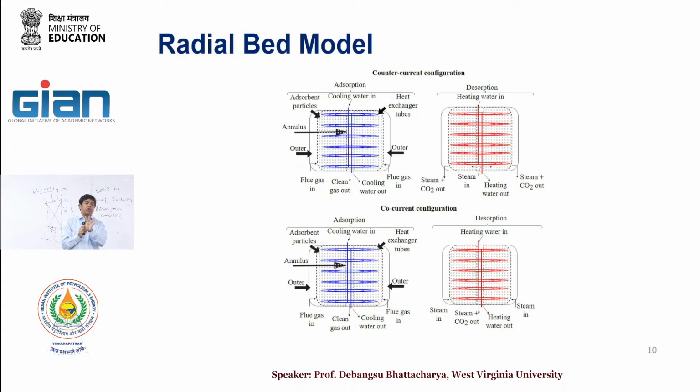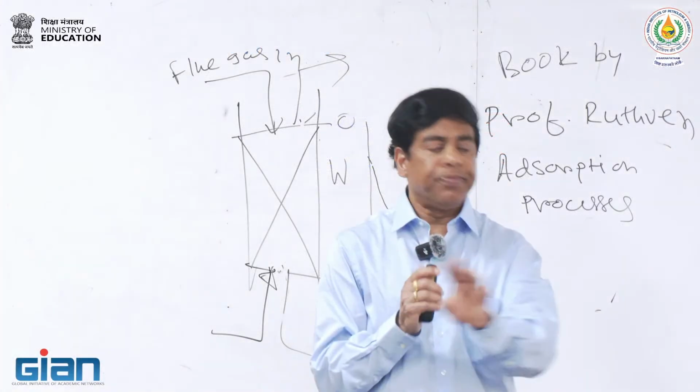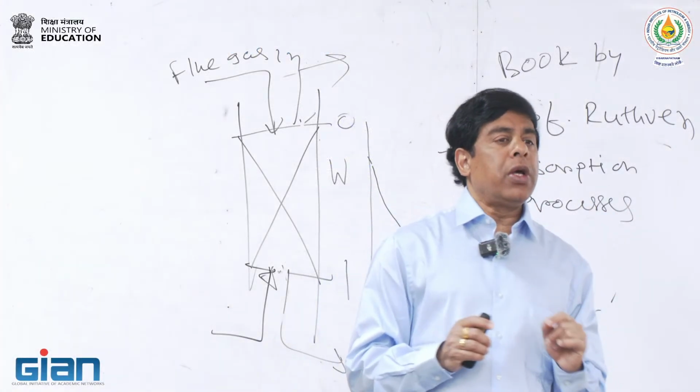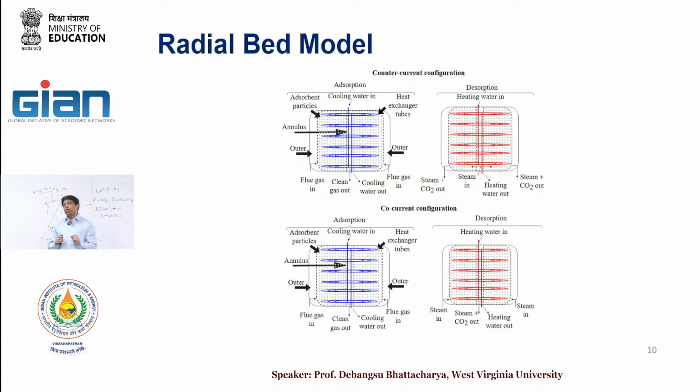What we did here is, now the tricky thing is that for the axial flow fixed bed, the heater design and others are generally something people have looked into, and it can be done. When you look into radial flow, this may be a little bit challenging conceptually, how to do it. So we thought about some options. I'm sure there could be other options that people can think about. But one of the configurations which we are suggesting is that it is fed through a ring.